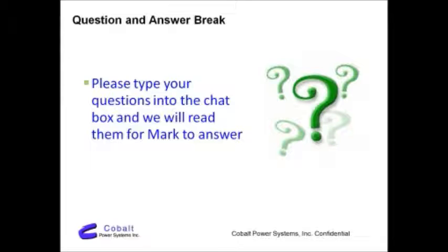Okay, so how about hailstorms and snow loads? Great question. How durable are these panels? So almost every solar panel on the market is guaranteed to not break with a 1-inch diameter hailstone impact in a 52-mile-per-hour wind. If you think about it, a 1-inch diameter hailstone is a pretty hard impact, and they have to pass a test where they can't break.